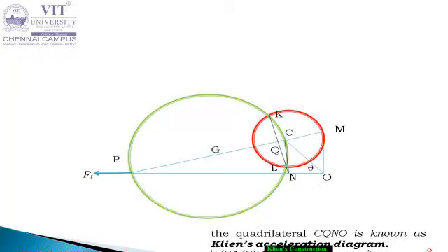We have already discussed using the relation L1 L2 is equal to K square. If you know K, that is the radius of gyration, you can directly find the point where the second mass is concentrated, that is D. Otherwise, one more method is there. You have to find out the point Z by drawing a perpendicular line from G, a line perpendicular to Z. So you have to fix the point Z. How can you fix it?